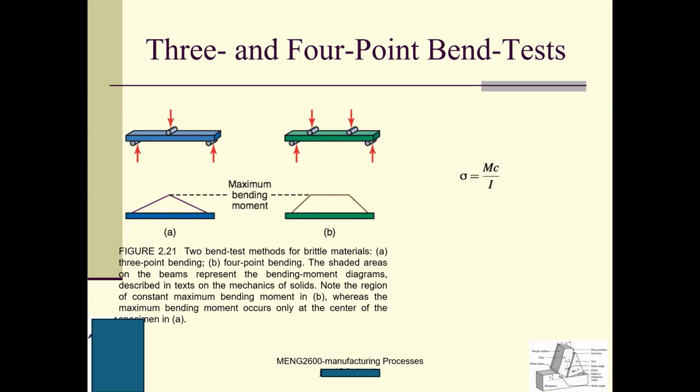So in the middle there must be some fibers whose length does not change. That is called the neutral axis. On this axis, if I put a fiber, its length will not change before and after you apply load. The c is the distance between the point of interest and the neutral axis of your specimen.